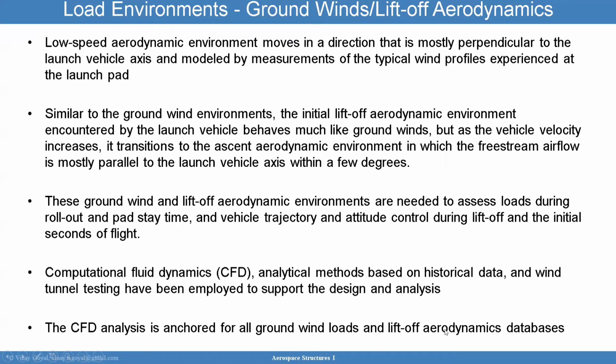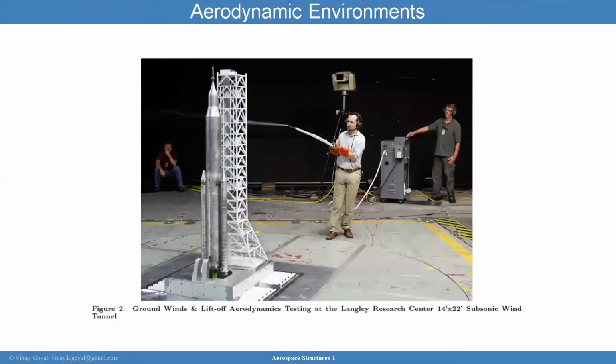You will have CFD analyses looking into this very carefully and making sure your models are anchored very well. Here's an example of a wind tunnel test, and here you can see a mock-up of a launch vehicle. This launch vehicle is going to be subjected to ground winds and liftoff aerodynamic testing to fully characterize the loading that the vehicle is going to experience.